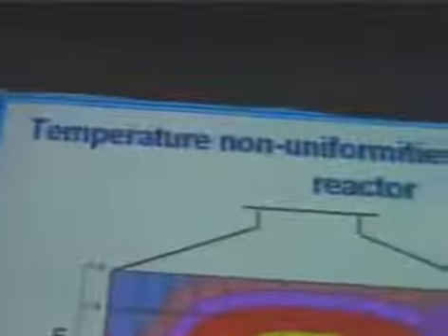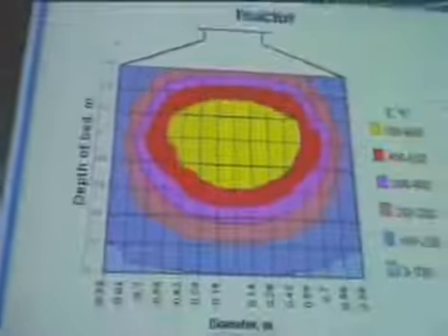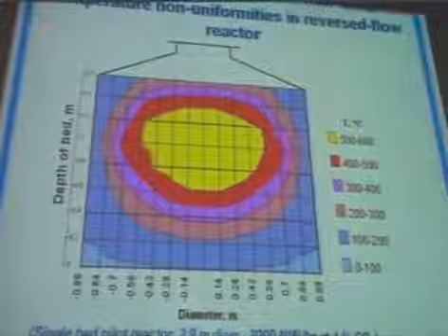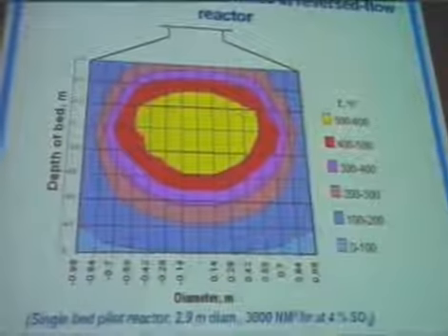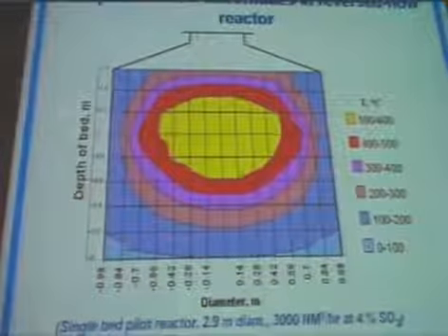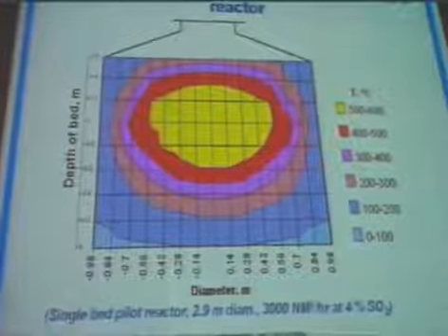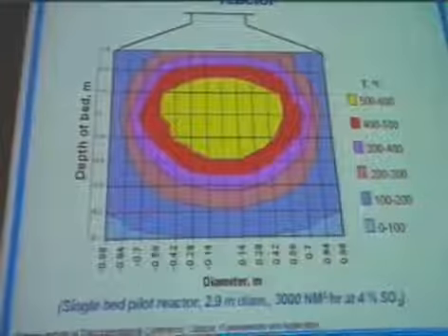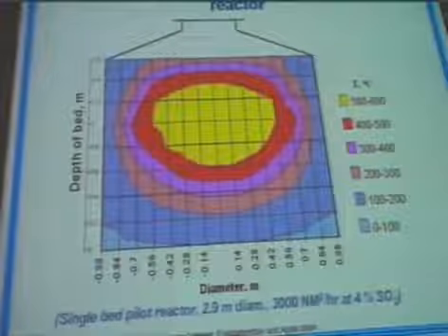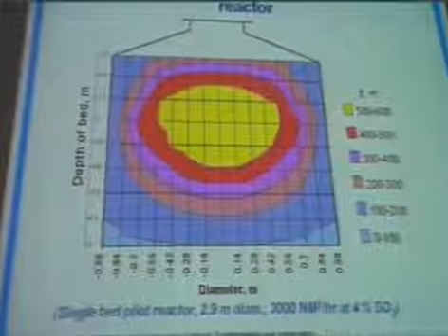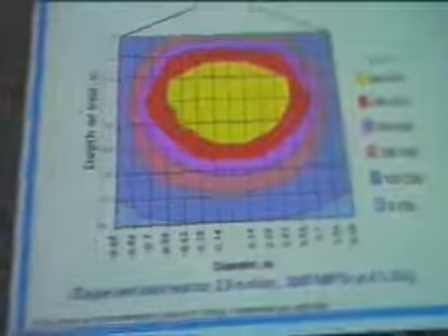Inlet and outlet is cold, but you can see that you have the cold temperature not only... I'm showing you this place. I need to show this place. Oh, I forgot. And you can see that the cold places were recognized near the wall, and this phenomenon created that maybe 20% of the gases are bypassed near the wall. And a few methods were developed to homogenize, to equilibrate the profiles of the temperature inside. I will tell about this in a minute.